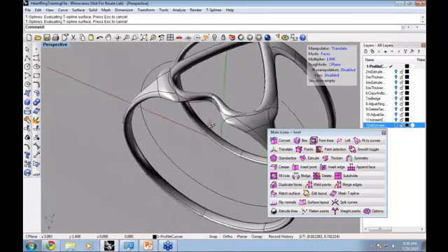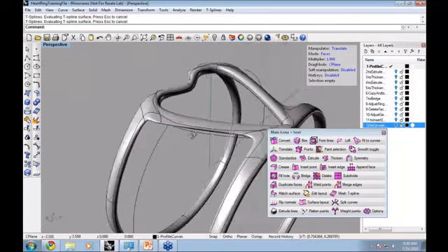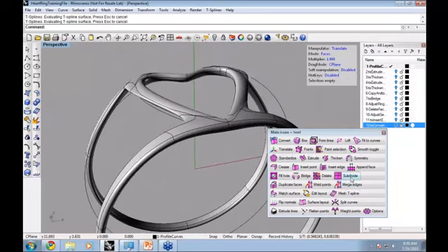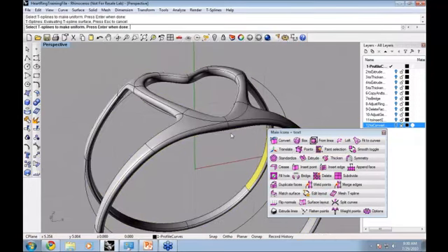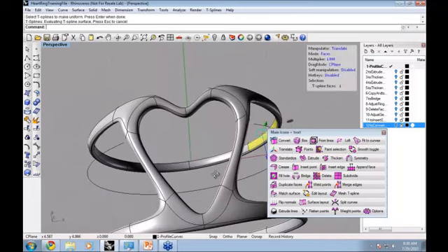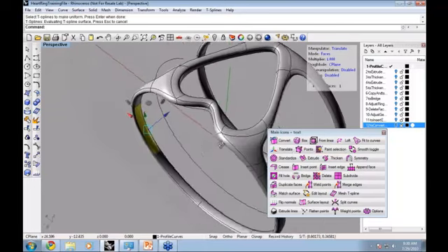Whenever you do operations like bridge where you're combining surfaces and it looks crazy afterwards, one thing that I always like to do after that is to run the make uniform command. So you do that by right-clicking on the edit layout button, and then after that, it does an amazing job at cleaning up the surface. Look how much nicer that looks.